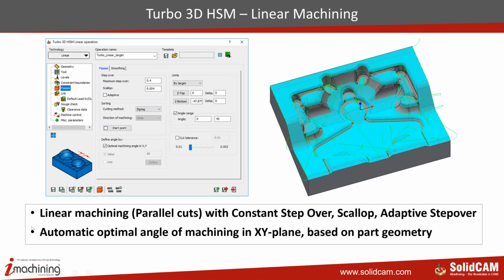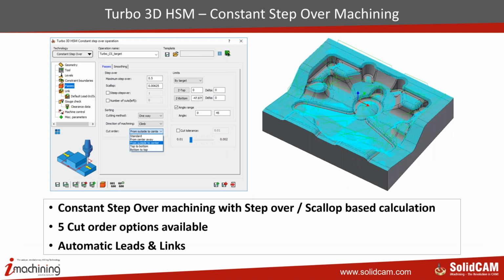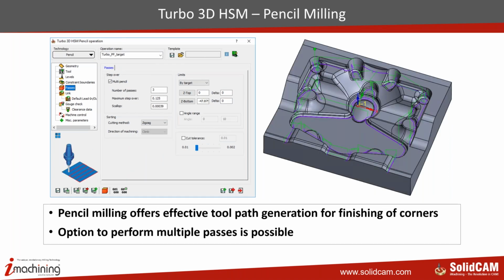And another very unique function which is available inside Turbo 3D HSM is a function called optimum machining angle in XY. So the moment you pick this function, Turbo HSM will take care of the most optimum angle to generate the toolpath in linear strategy. We also have constant step over machining strategy inside Turbo 3D HSM. We can also do pencil milling inside Turbo 3D HSM, where the pencil milling offers effective toolpath generation for finishing only all the corners.